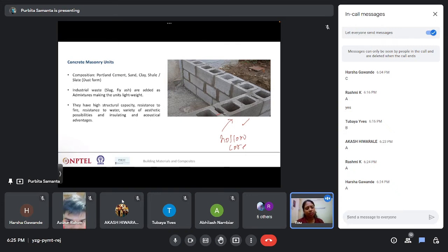We also studied, when we were talking about AAC, that a minimum amount of mortar is needed; in these joineries, maybe a little bit of mortar is being used. Apart from that, you get a very smooth and nice finish from outside as well, which is very different to when we looked at the brick work, right? So these are some of the reasons why we use the CMUs.